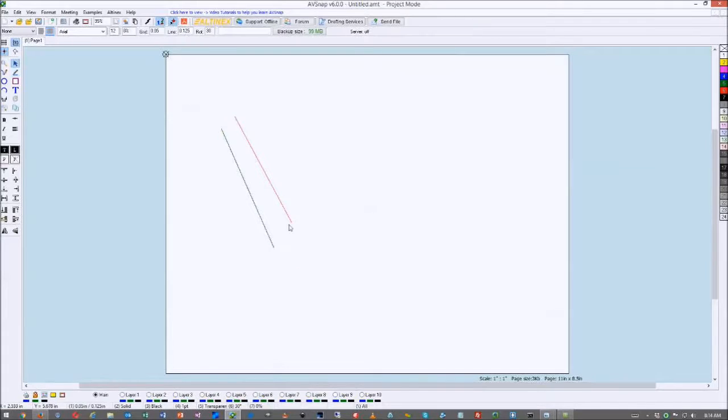So some people get confused because they change this, and they say, why did my line become red or green or blue? Why did my fill become different than what I expected? And the reason is because when you don't select anything on the page, but you adjust any of the settings, let's say a font size, transparency, anything, that will store it automatically as a default setting. And once it's default setting, next time you draw it, it's going to come back as a default setting.